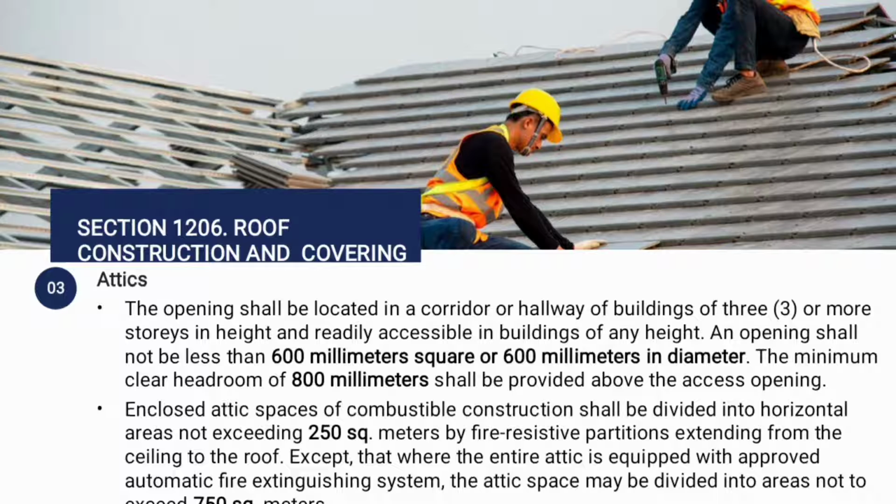And also the attics must be enclosed. Enclosed attic spaces of combustible construction shall be provided into horizontal areas not exceeding 250 square meters by fire resistive partitions extending from the ceiling to the roof, except that where the entire attic is equipped with an approved automatic fire extinguishing system, the attic space may be divided into areas not to exceed 750 square meters.